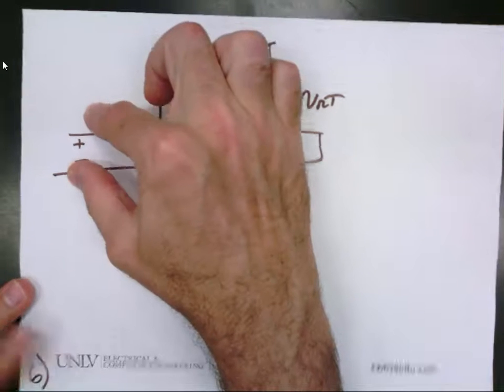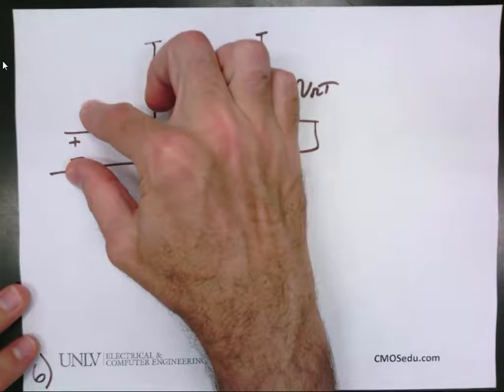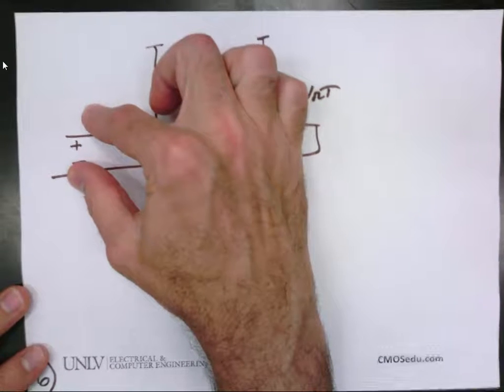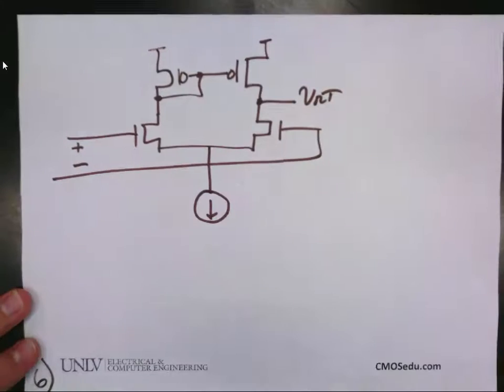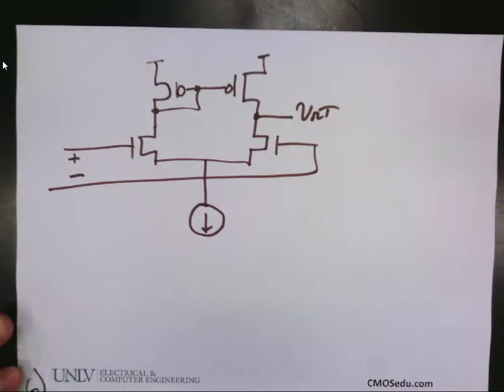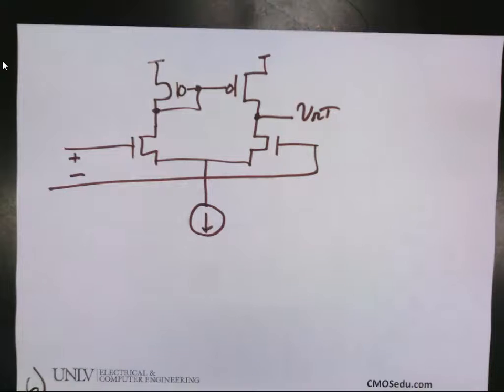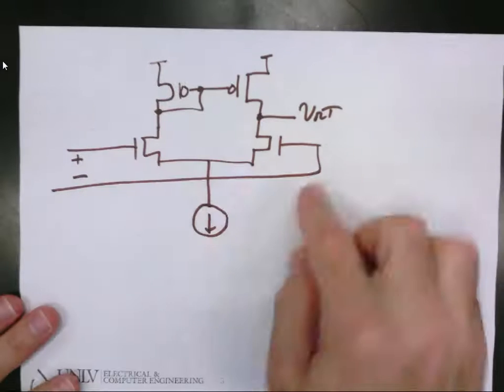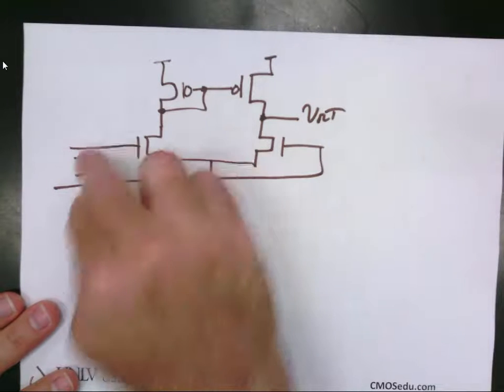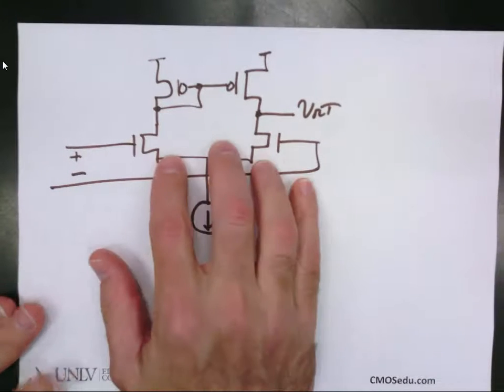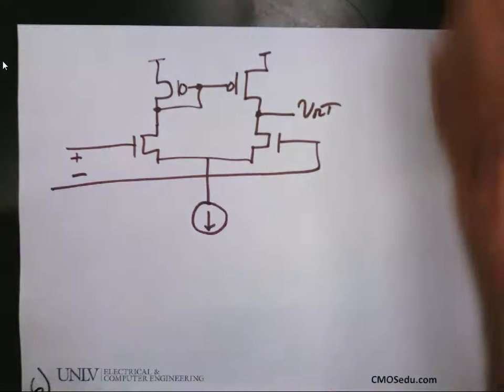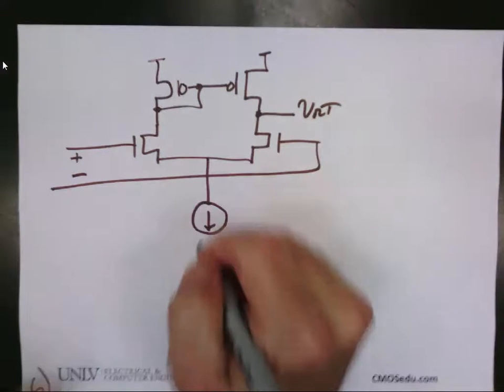A common problem that you might have already encountered in audio or in your labs is a 60 Hertz hum. You have the wall socket here and wires that are going around. They can radiate noise into your speaker and you can hear that hum noise. So if you go into your diff amp and that's moving back and forth, this will ideally reject it. So here, let's go through and explain that.